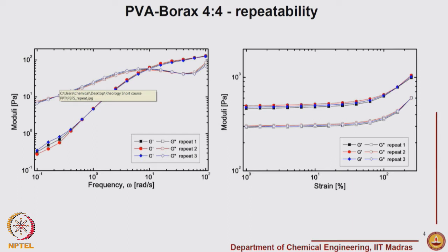So this data again is showing one such material. Here you can see that we are looking at oscillatory shear data, and this is a viscoelastic sample. At low frequencies you have G prime much lower than G double prime, and then they become equal at some frequency, and then G prime starts becoming constant while G double prime undergoes a minimum and then increases. During class we have already discussed this kind of viscoelastic material. We had seen that a supramolecular gel also has a similar response.